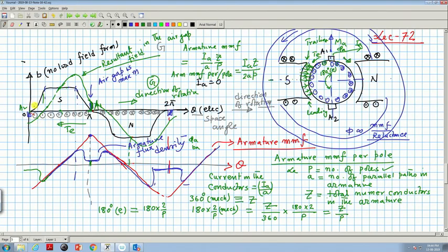Welcome to the 73rd lecture on Electrical Machines 1. In our last class, I told you how to get the resultant MMF distribution or B distribution in the machine, and the conclusion was that in the trailing pole tip the flux density will be concentrated, which we understood from our qualitative way of discussing things, but it is also